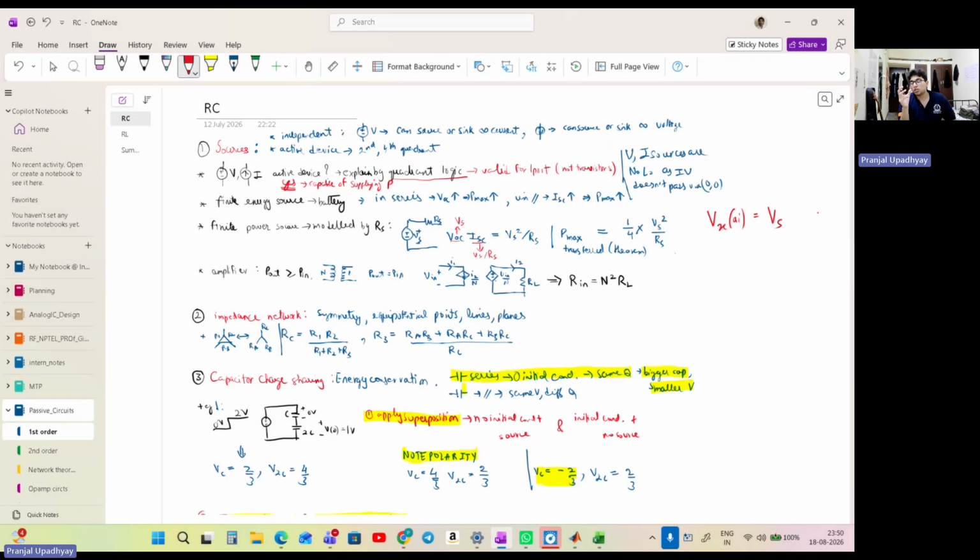That's the idea because our ideal voltage source, as we already discussed, will maintain a constant voltage across it, regardless of the current it is sourcing or sinking. So from this alone, we can understand that it is not following the principle of homogeneity, so therefore it cannot be a linear system in that sense, right? But we use it quite comfortably as a linear device in our circuit analysis. I still just wanted to discuss this small catch for people who are too much into maths or want to be mathematically correct. I did not mention this to confuse folks. Definitely in our circuit analysis, we use it rampantly as a linear system.